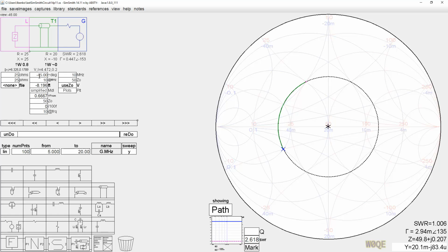So let's look at this piece of transmission line we've got. And let's say we don't want 45 degrees. What can we do about that? Well, there's a whole lot of ways we can change this length. We can right click on the end of this and drag it. That changes the length. We can put our cursor in here. It lights up the field in blue, telling us that it's been selected. We can enter a value in there. Once we enter any digits at all, it turns red or pink, telling us that it's edited. It has not been taken. This did not move. If we want this value to be accepted, we have to press either the enter key or just click somewhere else. I'm going to just click somewhere else. And now we see that it's been taken and it's good to go.